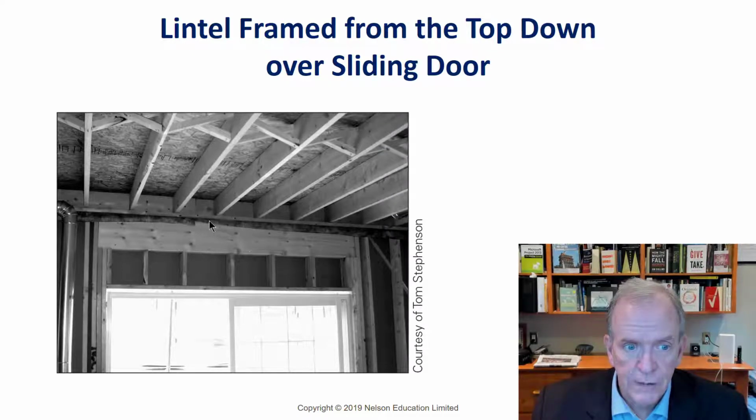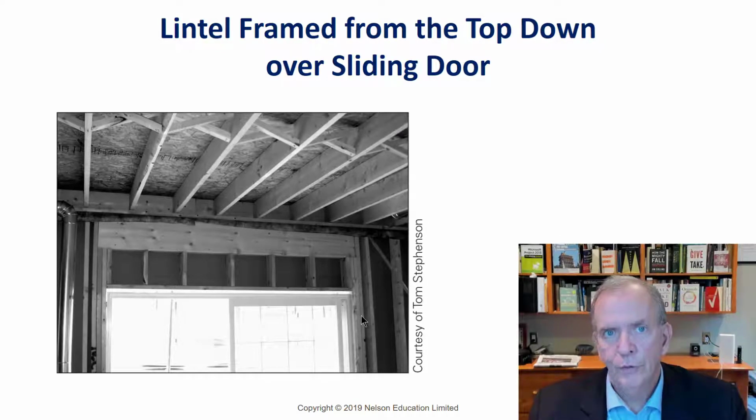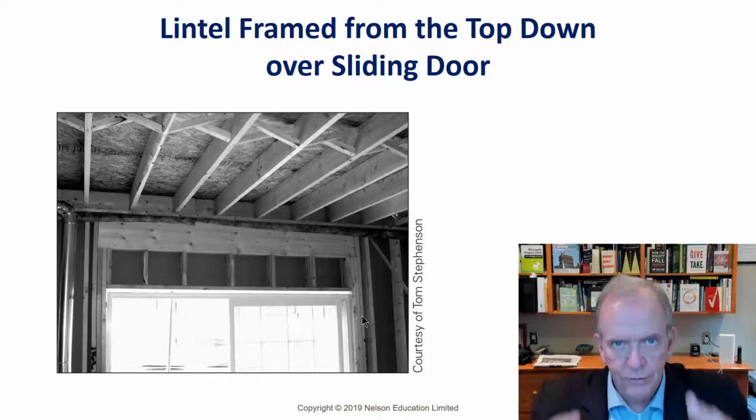The main thing is that the weight from up above is being taken on so that it actually spreads the load off to the sides. So that's very important from our perspective, that the weight that's up above gets distributed onto the lintel, and it transfers those loads to the jack studs, which transfer it down to the floor, which transfers it to the foundation wall, and so on and so forth down to the footings.